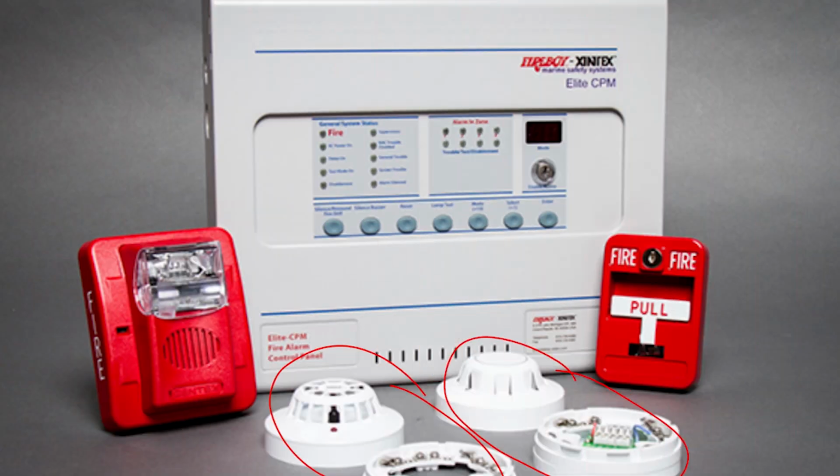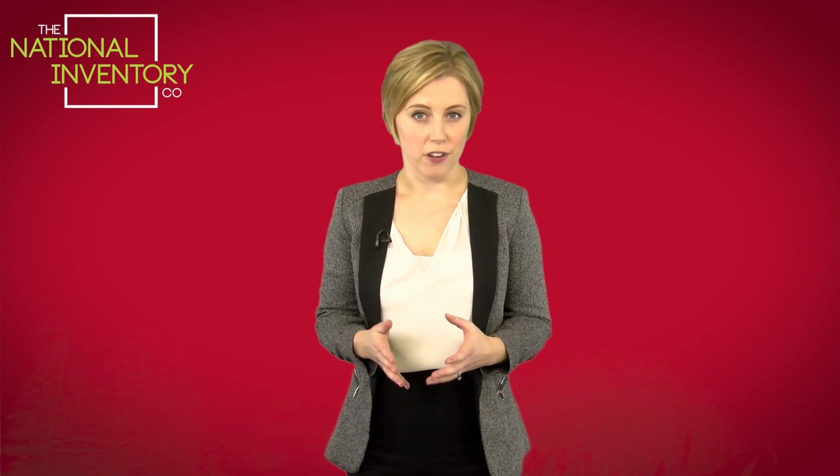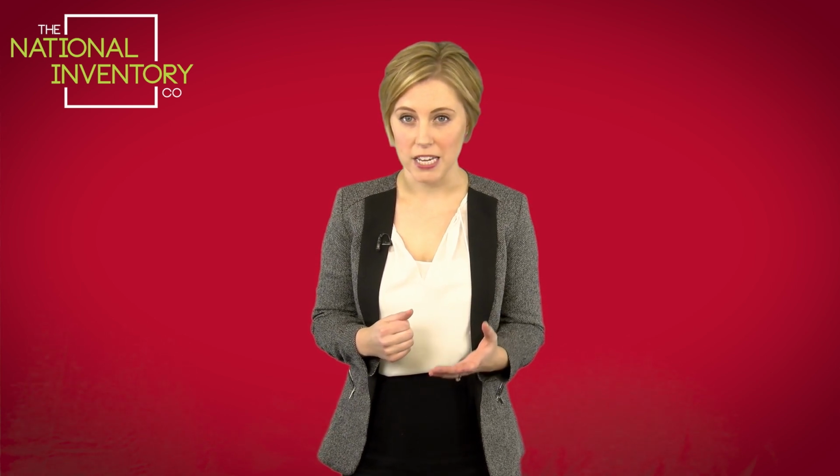We strongly advise you do not smoke test these alarms unless you are doing the full commercial alarm test, because if you do smoke test one of these alarms, it will trigger the entire building, including every flat within the building, and create a mass evacuation.